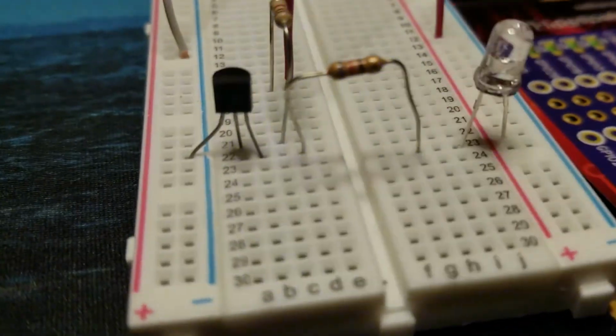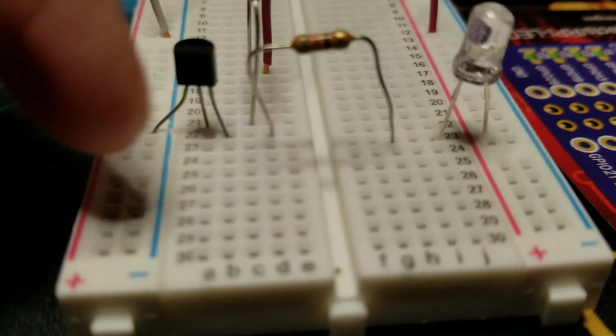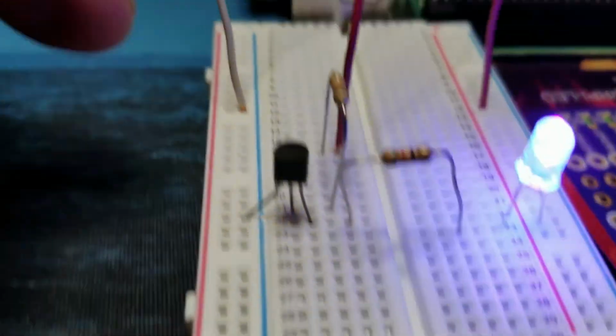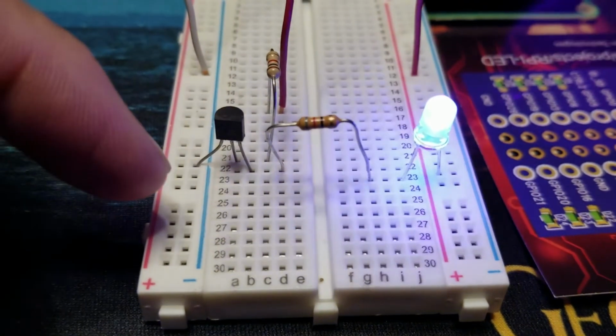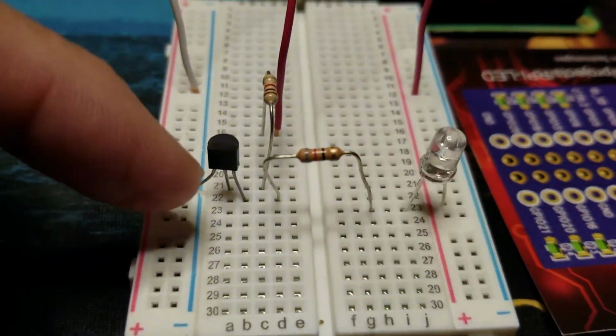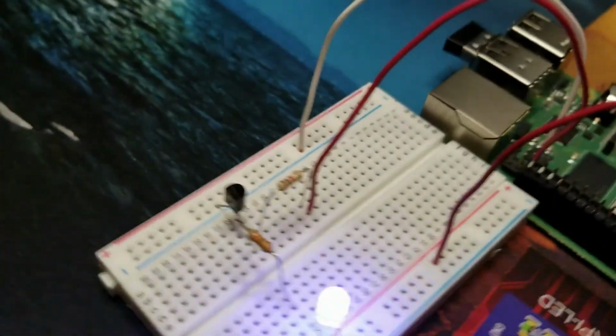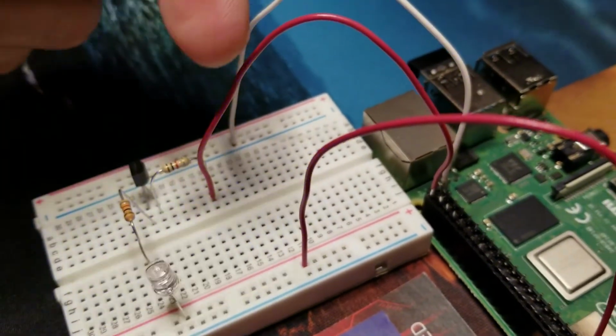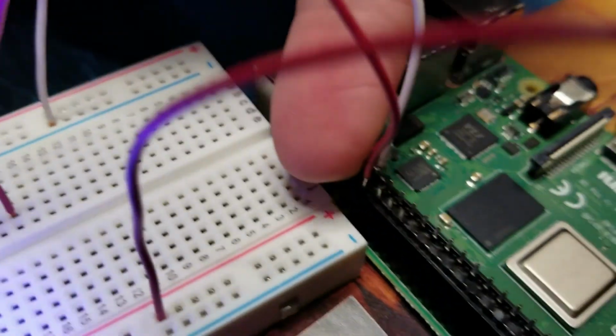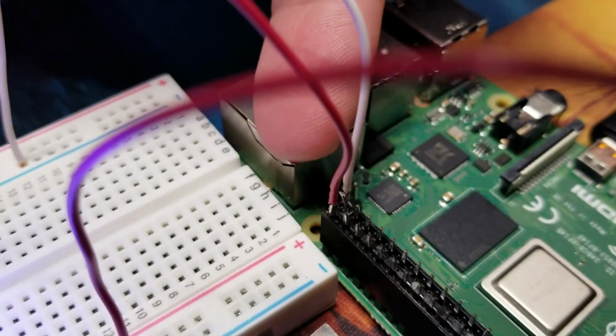You can see here's our transistor. The emitter is going here, which is the ground. Ground is coming from this pin here in our header, right here. This is the ground, right here. So that's coming into the emitter. Then the base is the center pin, which hooks to our 1K resistor, which is driven by GPIO 21, which is this pin right here, the red pin right here on the header.